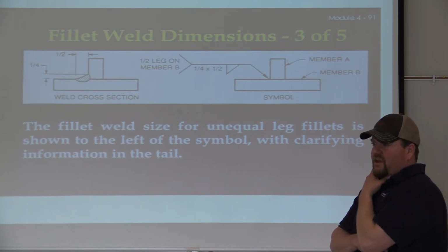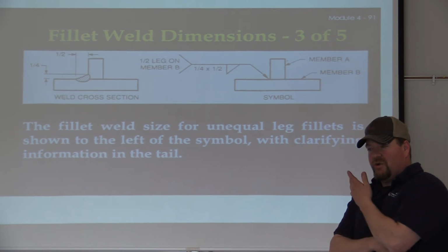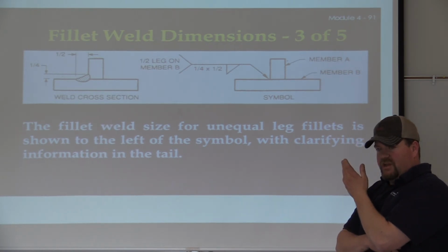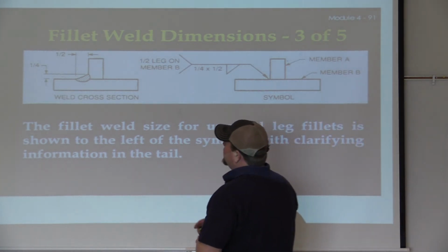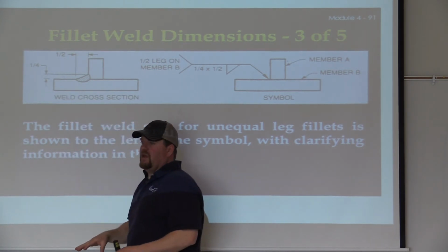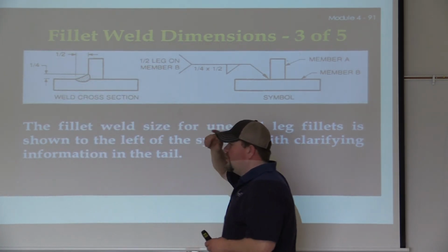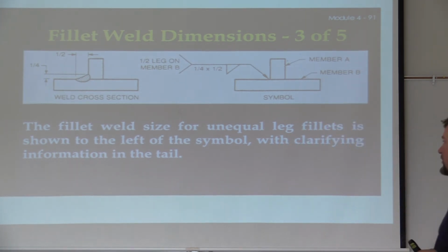But it's 20 feet in the air, and so forth. It's not structure bearing, it's just a pole, but it does have to have some support going up there. You might see something very similar to this, where the majority of your weld is going to be focused on the bottom plate and just a small weld on the top section, okay? Very seldom do you see it, but occasionally it can happen.